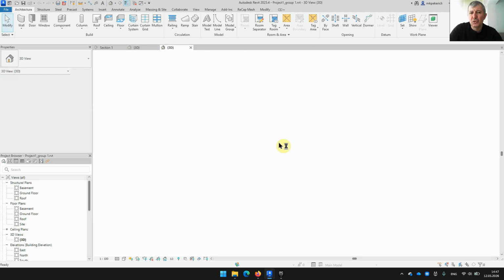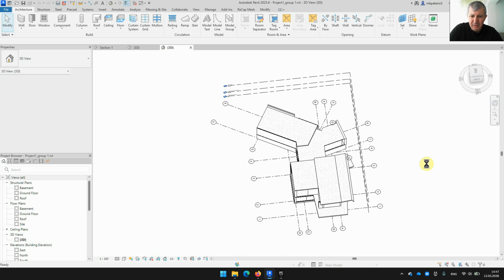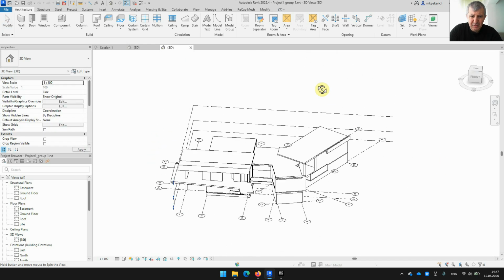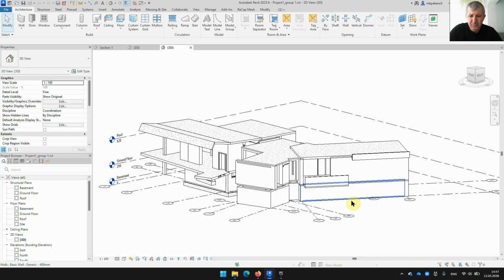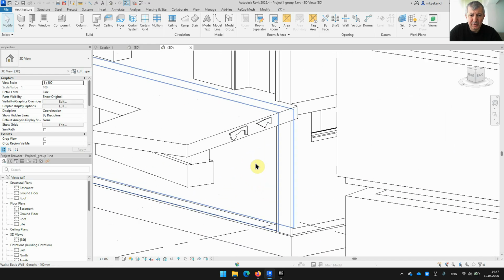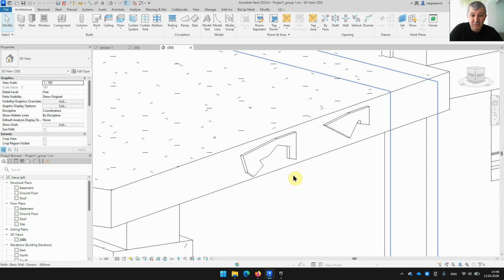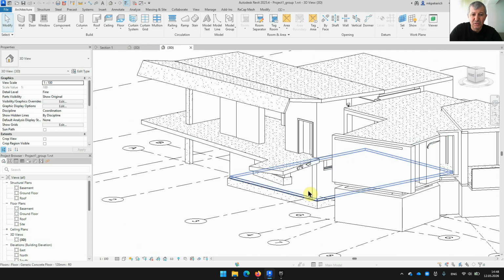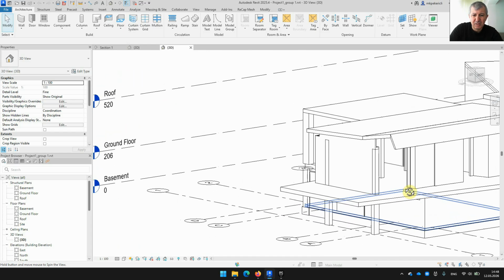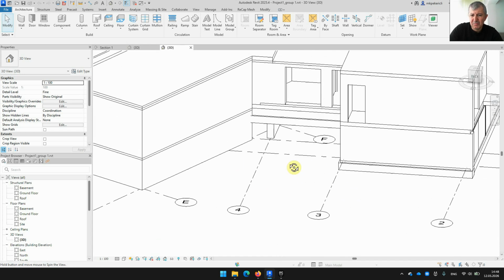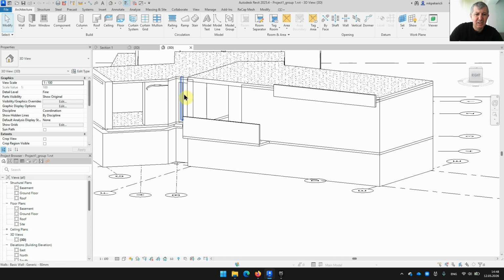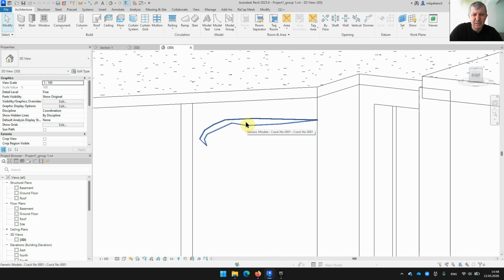So what you do is you use both drawings. Here we go. This is that building. Okay, and you use both the drawings and also the digital photogrammetry. Now in this case, we are adding extra information like these. Okay, so this is a biograph. Biograph is basically some deterioration in concrete that we are documenting. Okay, so we added these, for instance. I wonder if there are others added. Yeah, here I think we have something here. Yeah, this one is a crack.